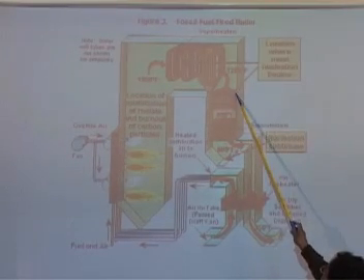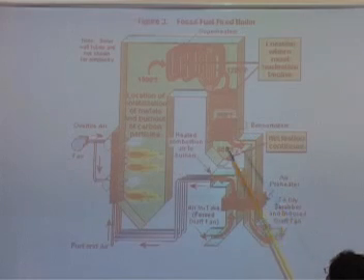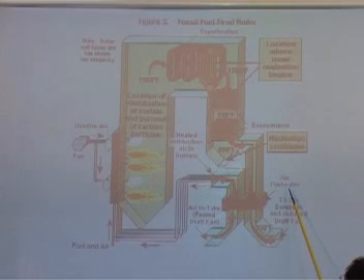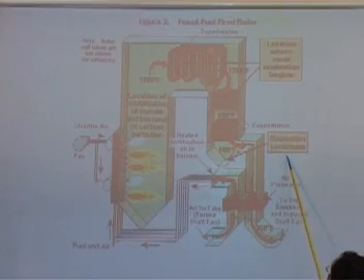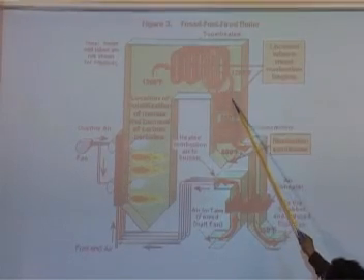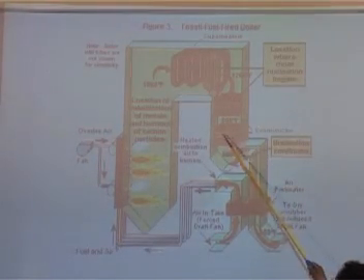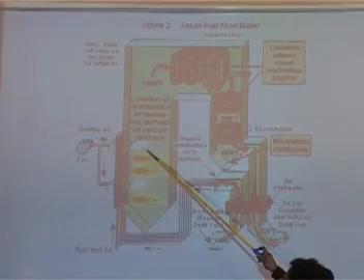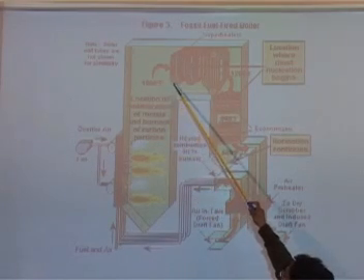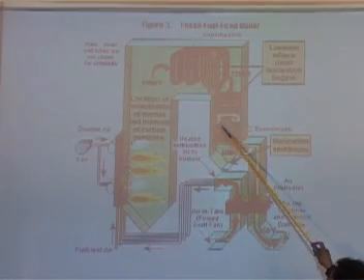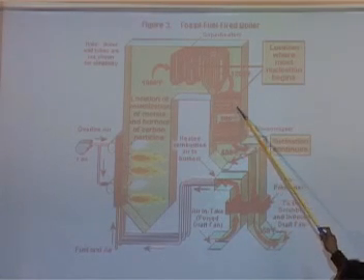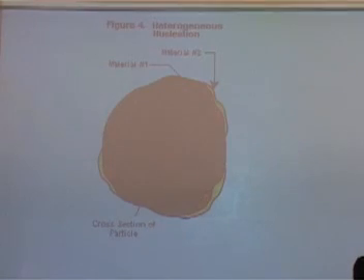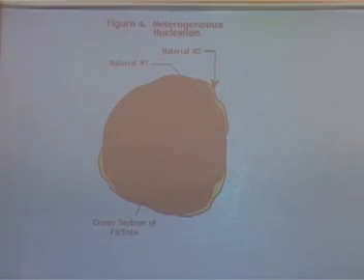The moment the temperature drops, some nucleation can occur right here. Largely it is talking about the nucleation which can occur right inside the process. Because you need a certain temperature. Suppose the burnout is not complete, the vapors will continue to go up, and there is no opportunity for the vapors to be burned out, so the vapors escape and through nucleation they can become particles. And this is something, nucleation, you should understand. Maybe we will talk again in the next class.